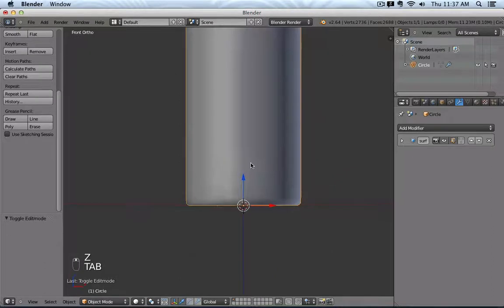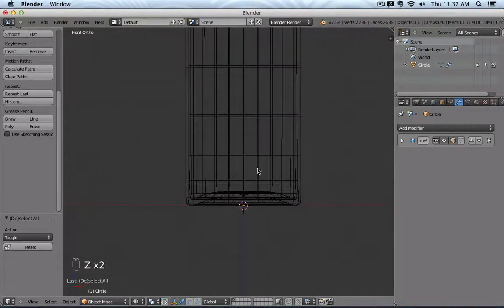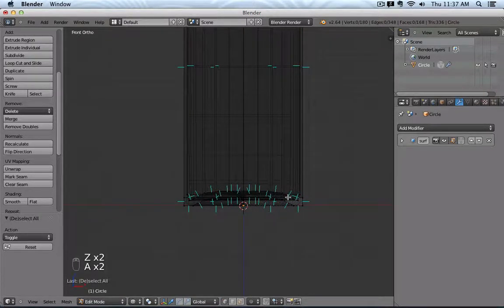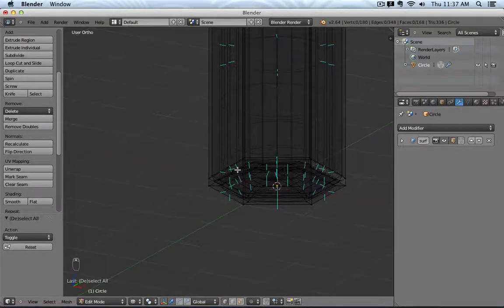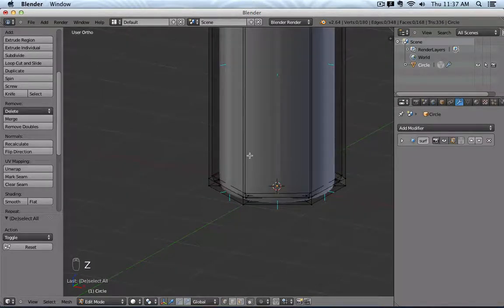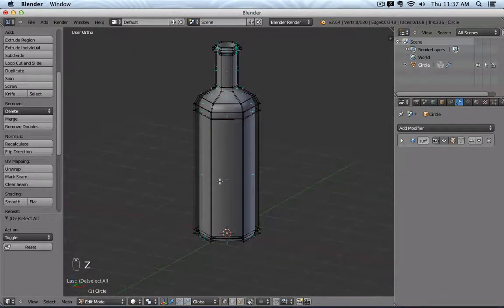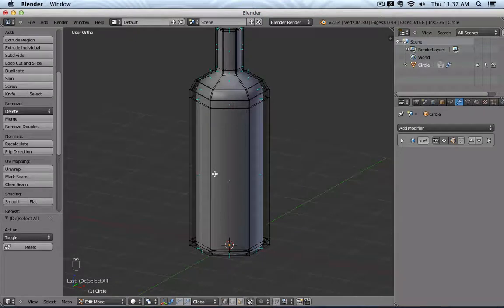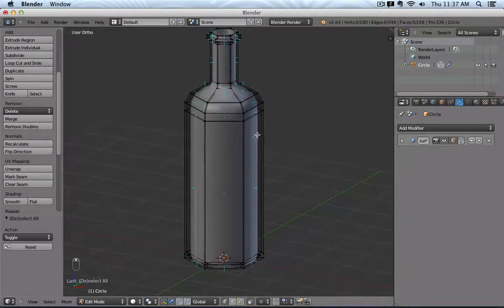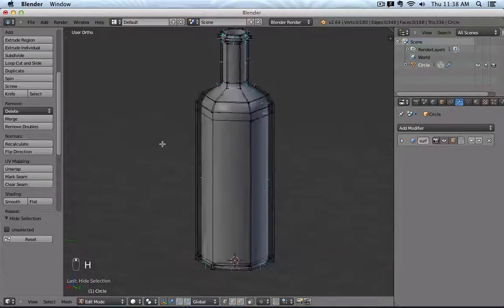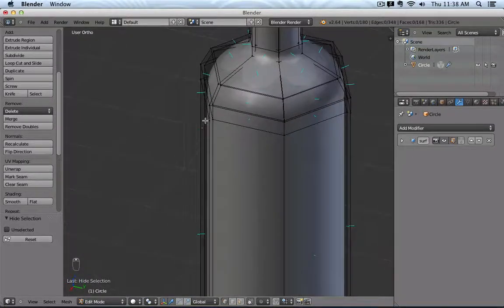Okay, so you saw that very often I worked here with the wireframe mode, and then I tried carefully to analyze my polygon mesh, and by clicking on it try to make sure I was really working on the inside mesh. But there's also a way to hide, for example, the geometry. Let's say the outside shell I would like to hide. Well, I could, for example, click on a point and press H. Then it hides that point, and it hides all the elements that are connected to that point.